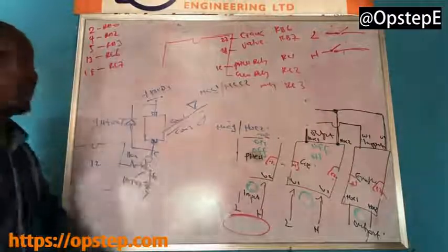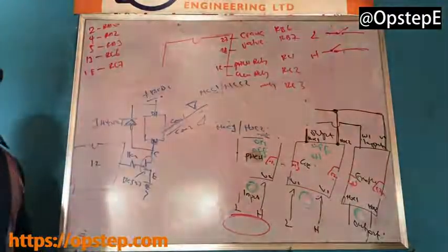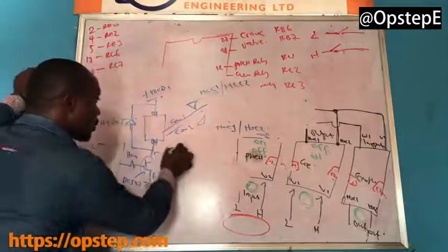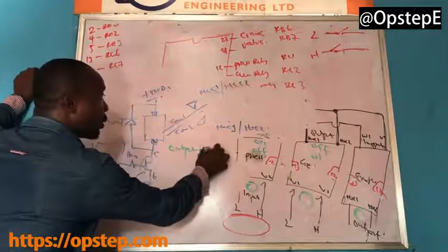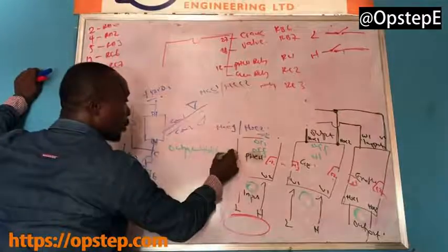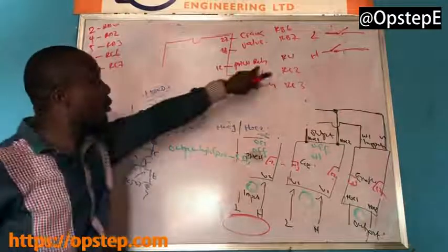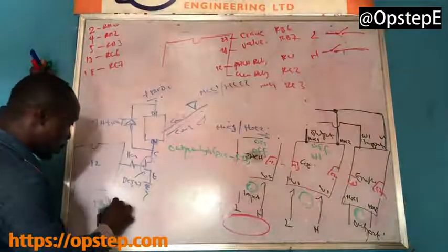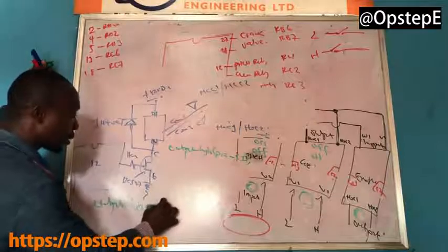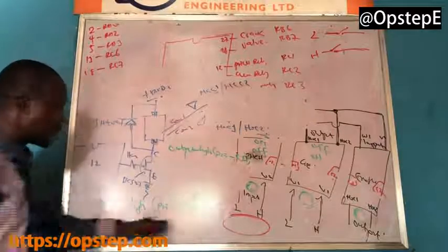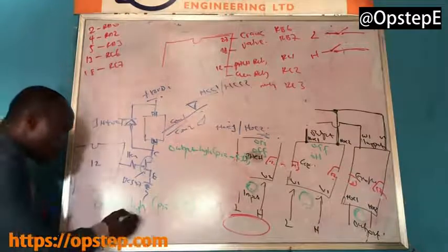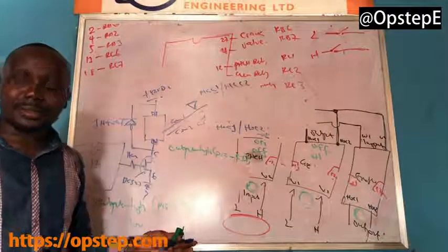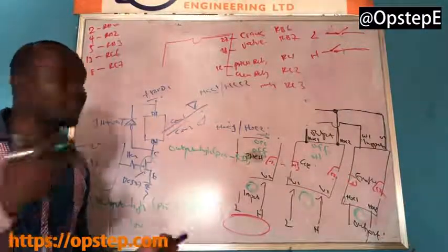So that is set. Now, if you want to turn on any of them, it's the same thing. When you want to turn on the one for NEPA, just say pin C1. Do you get it? If you want to turn on the enable, pin C3. Do you get it? And when you want to turn it off, you just have to put what? A low on that particular pin and it goes off. Those are the instructions for putting it on and off. Just the way you have the relay.